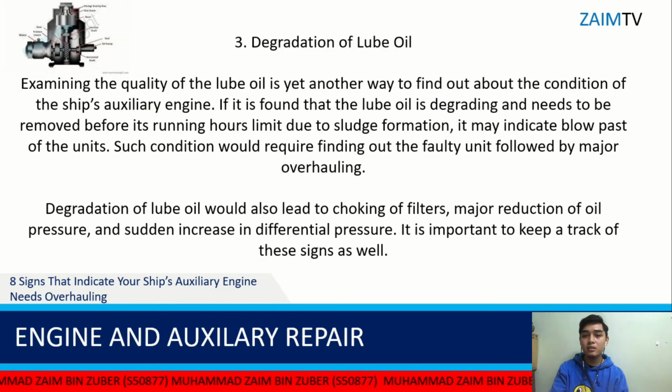The third sign is degradation of lube oil. Examining the quality of the lube oil is yet another way to find out about the condition of the ship auxiliary engine. If it is found that the lube oil is degrading and needs to be removed before its running hours limit due to sludge formation, it may indicate bypass of the units. Such condition would require finding out the faulty unit followed by major overhaul. Degradation of lube oil would also lead to choking of filter, major reduction of oil pressure, and sudden increase in differential pressure. It is important to keep a track of this sign as well.